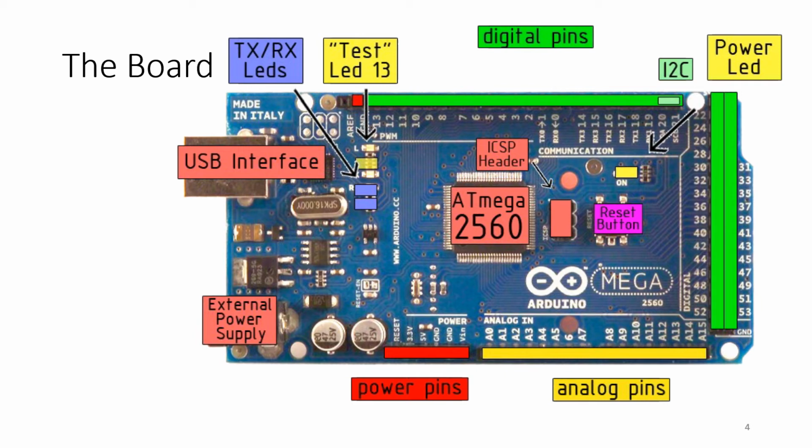There is an inbuilt LED available in this board to check the high and low value while operating in the software. This LED is connected to pin number 13. So if you want to test your program, you can give the program signals to pin number 13 and check the inbuilt LED available on the board.